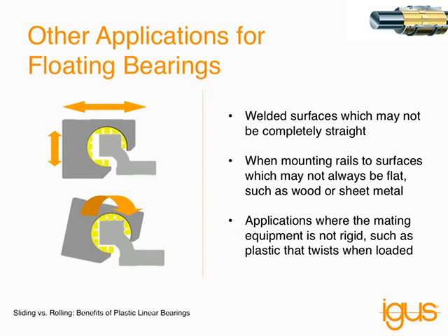A question you might be asking yourself is, well, if I put my drive force directly centered in between the two bearings or rails, do I need to use a floating bearing? The answer is no, but you can still benefit from the fact that it's much more forgiving for angular or any misalignments between rails or shafts.